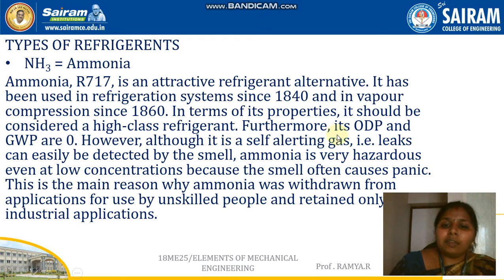However, it is a self-alarming gas, that is, a leak can be easily detected by the smell, as ammonia is very hazardous to the environment. This is the main reason why ammonia was withdrawn from applications for use by unskilled people and retained only for industrial application. If we use ammonia in the house and there is any leakage, it may lead to many accidents. So to avoid that, ammonia is used as a refrigerant only for industrial purposes, where there will be skilled operators.